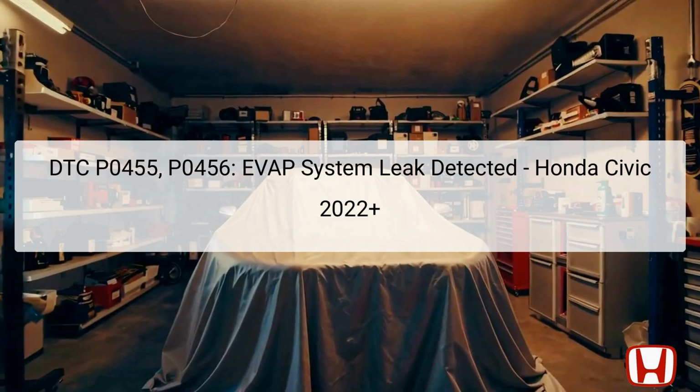The EVAP system's main purpose is to prevent fuel vapors from escaping into the atmosphere by capturing them in a charcoal canister until they can be burned in the engine. Important components involved in this system include the EVAP canister, purge valve, and various hoses connecting these parts. The location of the EVAP canister is typically near the fuel tank, while the purge valve is found in the engine compartment. When a leak is detected, it can lead to potential troubleshooting tasks to identify and rectify the issue as per the Honda Service Manual guidelines.